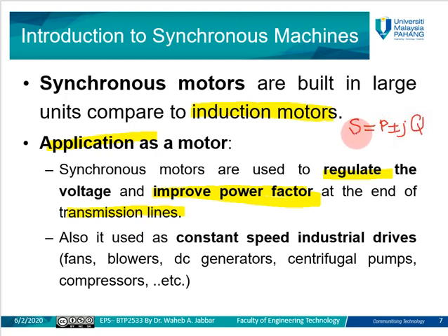So in the case of using the synchronous motor, we are going to improve the value of Q, which is produced with the leading power factor. So synchronous motors here are used to improve the power factor. By supplying negative reactive power into the grid, it will improve the overall voltage of our grid.